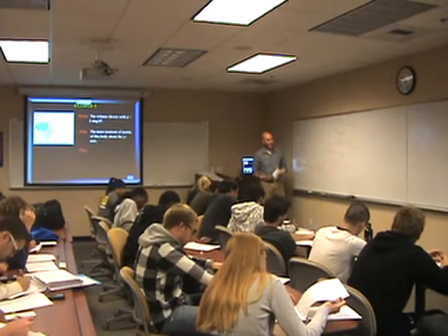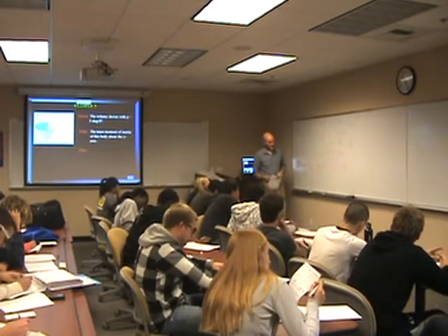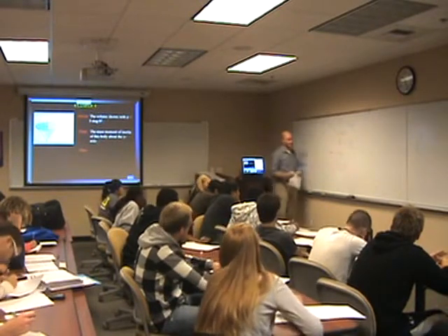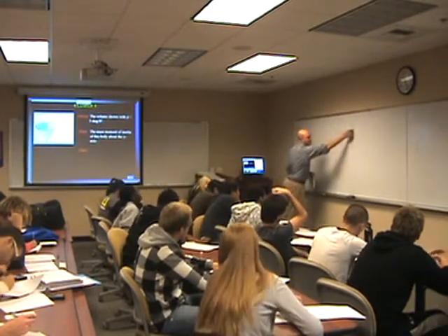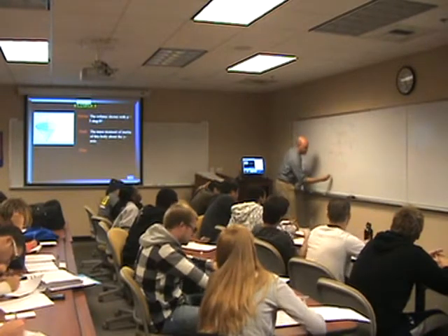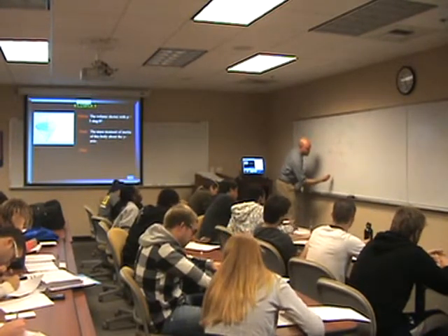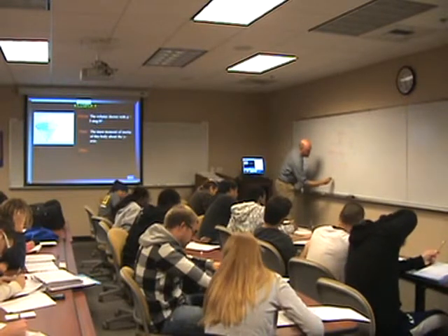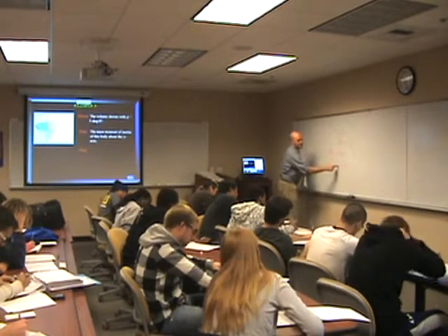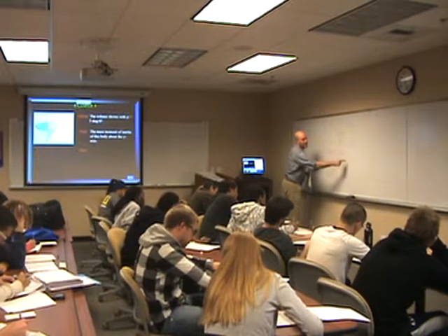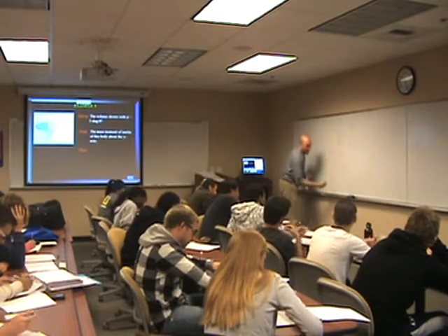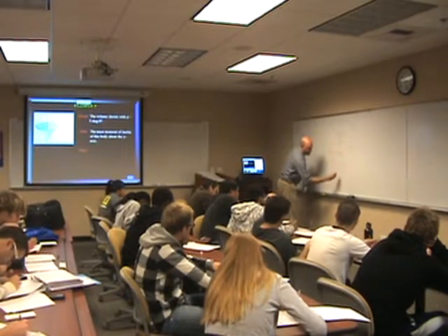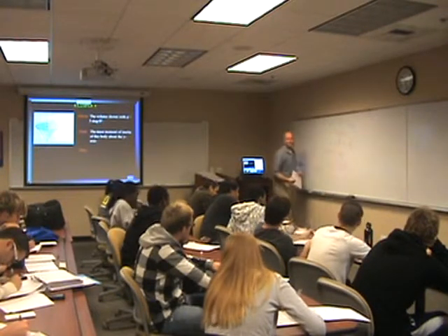Now we're integrating in y, but now we have x in there, so what do we need to do? Substitute. We have the relationship between x and y squared. So this is equal to the integral from 0 to 1 foot of rho pi, and we have x to the 4th, but x is equal to y squared, so it's y squared to the 4th.